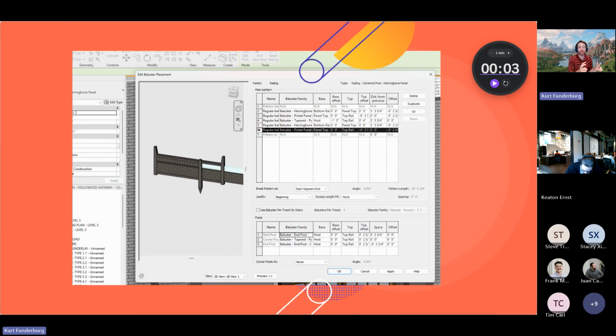So these are set up as panels, which are another thing. Like if you've done glass panel railings and stuff like that, where every so often there's a baluster, but most of the railing is a panel, and so this is a lot more complex because it's dealing with the overall length of the rail, and then I'm wanting to half that, and that's where the mid baluster sits, and then I also have the panels within that that are justified. But this allows us to have that middle pyramid cap right in the middle, and then I'm figuring out the dimensions for the panels to make sure that those fit.